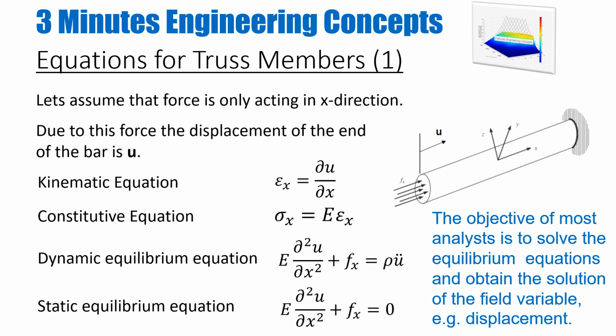Just to recap what we have covered until now, this slide shows you the kinematic equation which relates displacements with the strains. Next, it shows you the constitutive equation which relates stresses with the strains. And finally, the balance equations which are based on Newton's law, that is, the sum of all the forces should be equal to 0. These are the strong form of equations, so everything is satisfied in a very strong way.